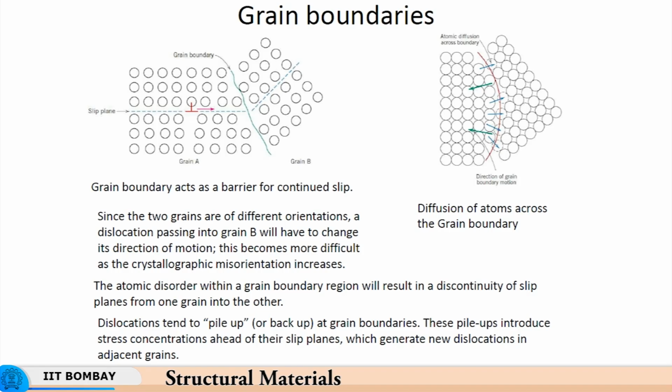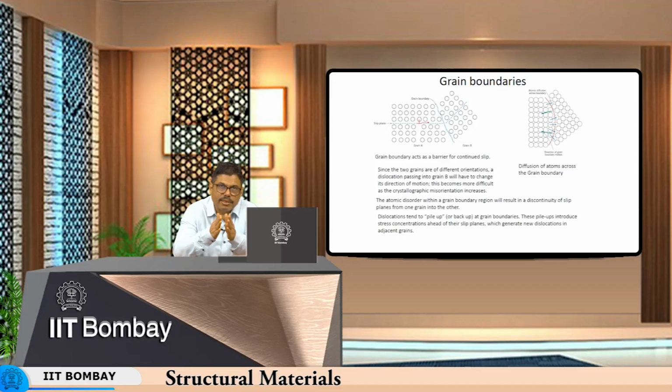So the initial process was to compress, and the change in shape was permanent. Then you extended the cylinder back to its original height h, and again the deformation is permanent. So this permanent deformation is the result of a permanent event called dislocation movement. The dislocations do not come back to their original positions because you have pulled the material back to its original height h. So basically what it means is that permanent deformation continues to add dislocations to the crystal.